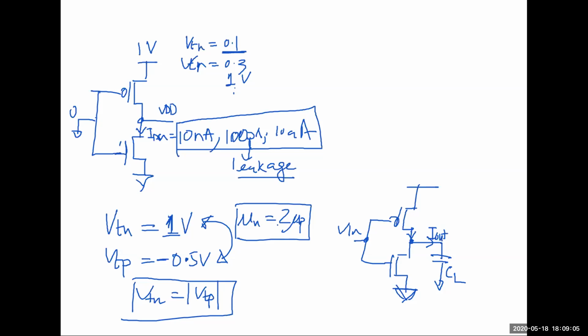The only thing I would warn you about is that you've said in the linear region it will follow Ohm's law. That is only for small VDS, just to approximate and make your life easier. But if it is not small, then you have to use the nonlinear equation, and you obviously can't use Ohm's law, right? Ohm's law is only for a linear resistor.